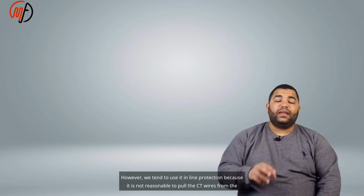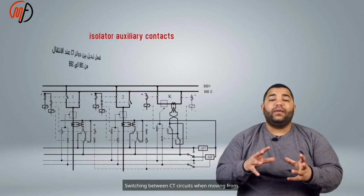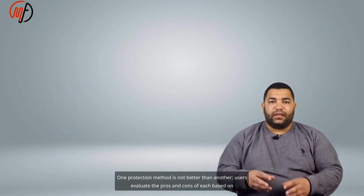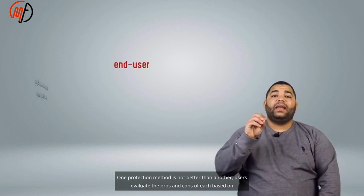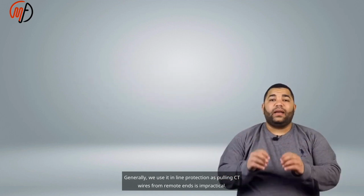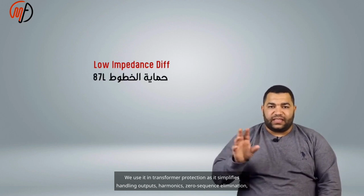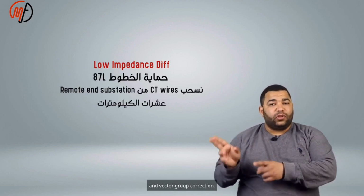However, we tend to use it in line protection because it is not reasonable to pull the CT wires from the remote end. Generally, we use it in line protection, as pulling CT wires from remote ends is impractical. We use it in transformer protection, as it simplifies handling outputs, harmonics, zero sequence elimination, and vector group correction.